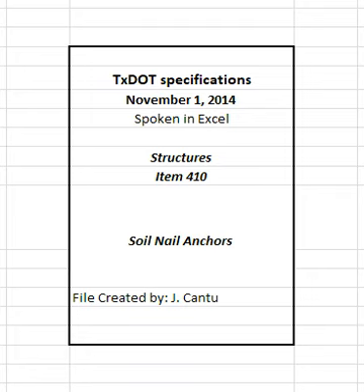Do not use grout mixed in a mobile continuous volume truck mixer. Provide a grout mix with a minimum water cement ratio of 0.4 and a minimum specific gravity of 1.85. Test for specific gravity in accordance with TxDOT 130E. When a sand cement mixture is used for grouting soil nail anchors, provide a grout mixture with a minimum slump flow of 20 inches. Test the slump flow of the grout in accordance with ASTM C1611.